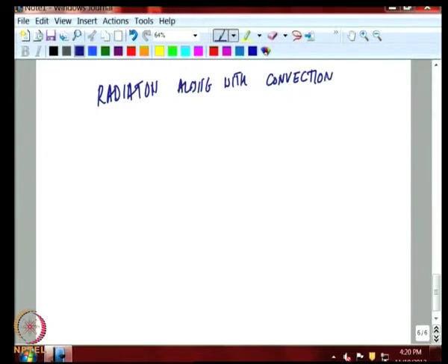So, you need to address the issue a little more carefully than the conduction problem we did, but we can still do the problem in a very simple context by assuming flow over a plate, and since our aim is to primarily understand the role of convection in a qualitative way, we look at the simplest problem in convection, when we assume that the fluid flowing over the plate has a single velocity equal to u infinity.